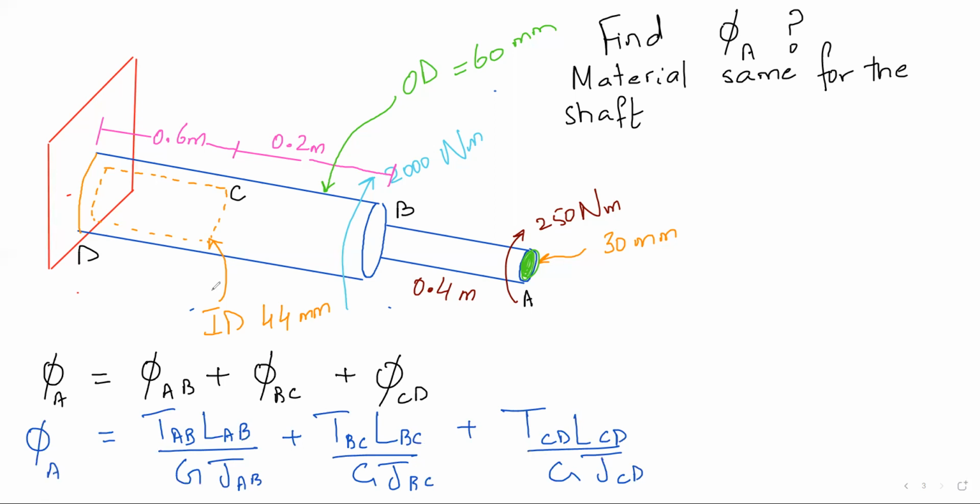And now you can finish the question quickly by saying keep making the cuts. You make a cut. So where would be your first cut? Of course, it is a hole that starts from the support, goes all the way up to 0.6 meter. So make a cut through the hole. Are you following me, everyone?